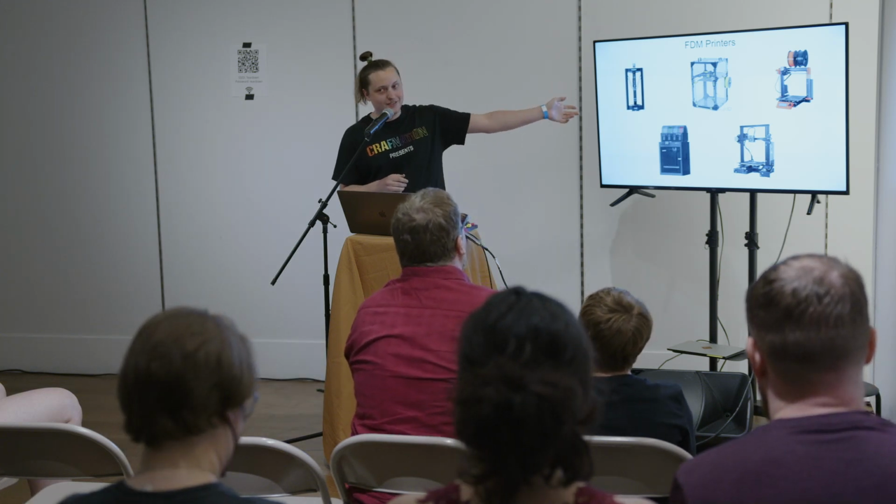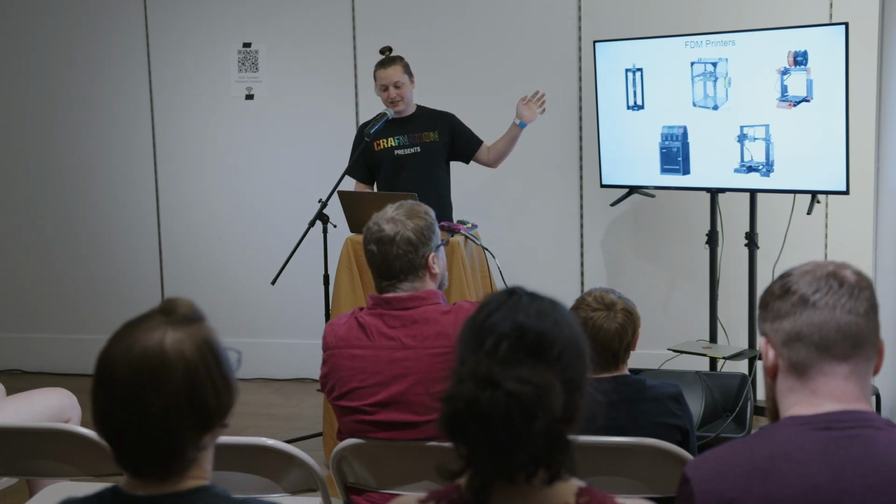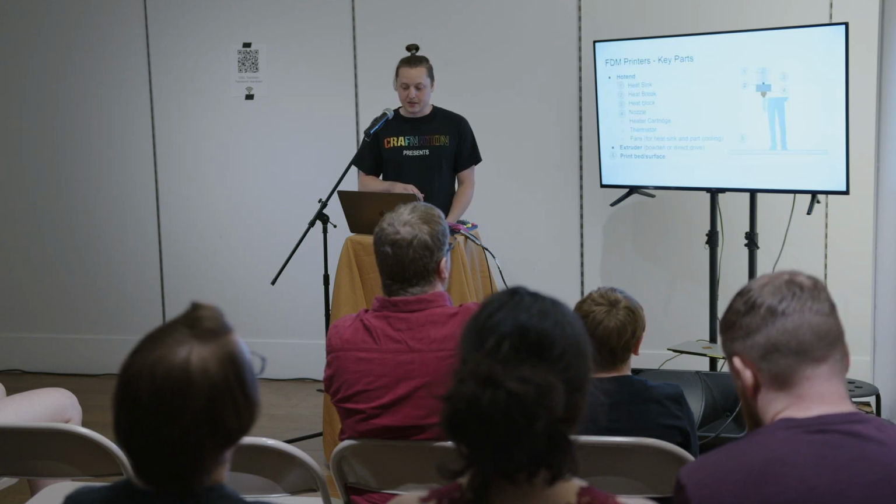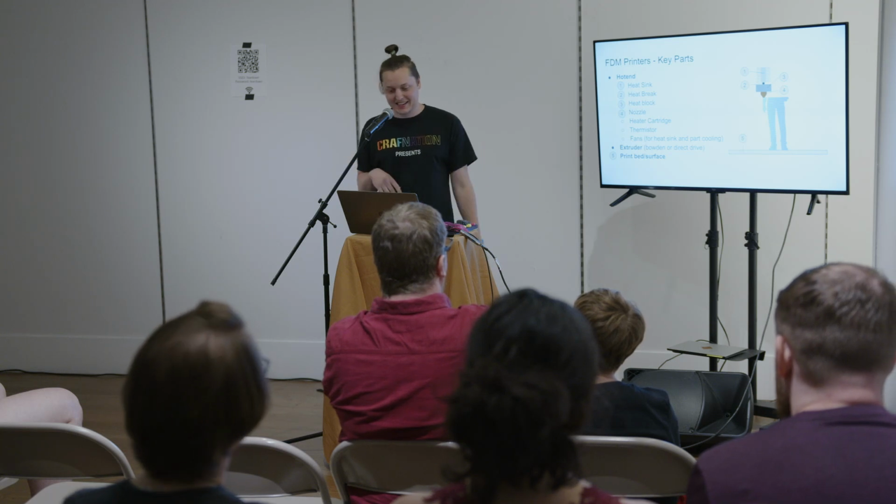This is a variety. I'll talk about each of these, and I'll have these pictures when I talk about each different type. For FDM, the key part of how it works is the hot end, which takes that plastic and spits it out in each layer. It essentially acts like a small hot glue gun on a CNC machine, so it's controlled by a computer to accurately place down hot plastic.